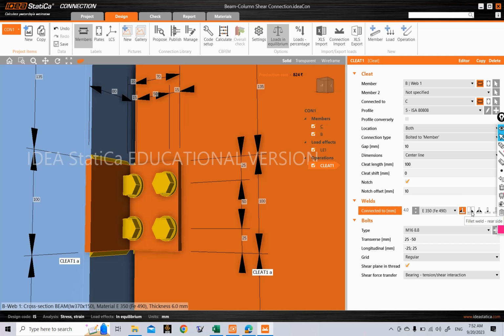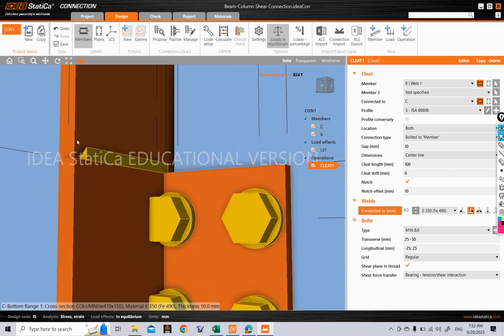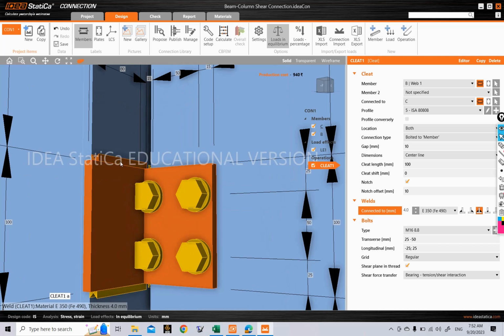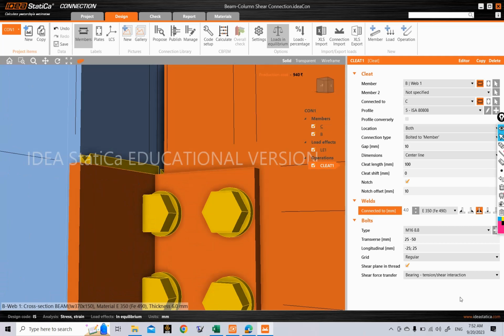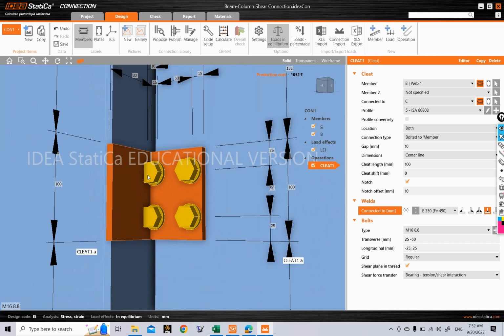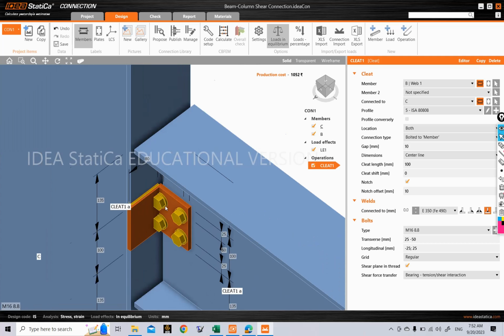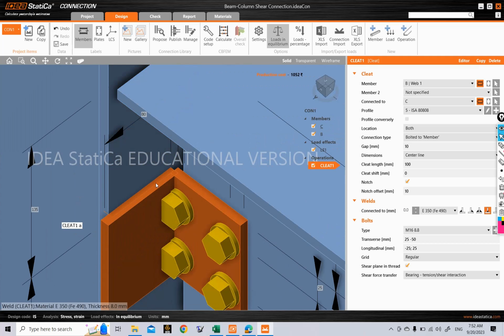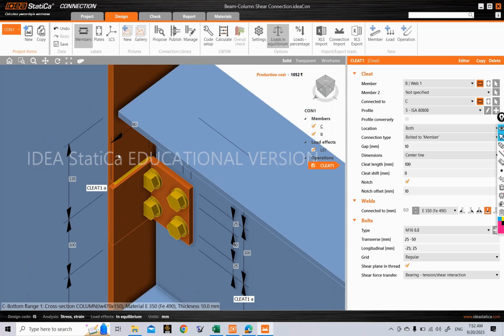If you choose this fillet weld back side, you can see that this welding, the triangle shape of our weld, changes. It changes from this to this. So of course this is not the type of welding that will be performed in our field. You can also choose this on front and back also. Again, this is not the type of welding that will be performed in field. Practically this is not possible. You can also select full penetration butt weld, such that now you can see that the butt weld is being performed at the back and there are no fillet weld here.